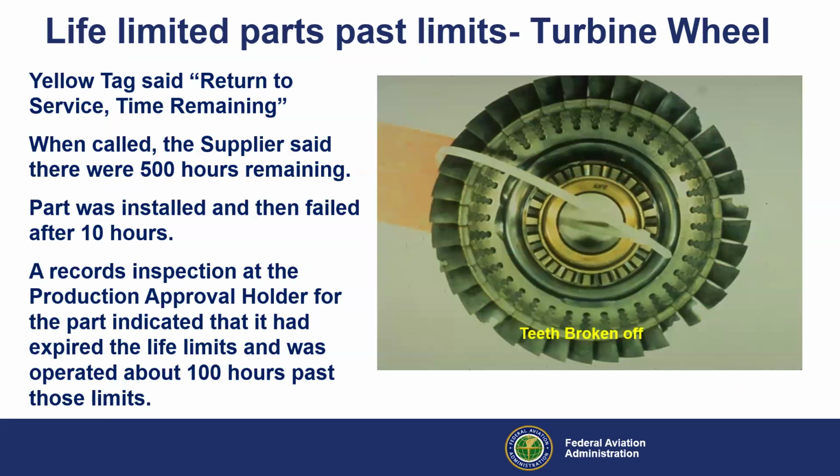Life limited parts, past limits. Here's a turbine wheel. The yellow tag said return to service, time remaining. It didn't tell how many hours or anything. And so when called, the supplier said there were 400 hours remaining. Well, the part was installed and it failed within 10 hours. So they did a records inspection, called the PAH, and found that this was actually 100 hours past the limits.